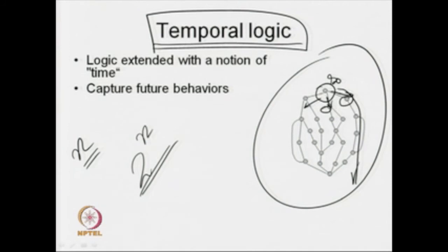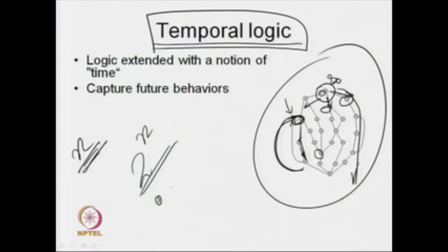And here you just see that I am in this state at a particular time. Now, here the time is different. Again you see that here I am going back to this particular state. So, this is the execution trace, going back to this. Now, this particular state basically gives the binary encoding of my n input symbols, because I define this state with these particular signals only. Either this signal is high or the signal is low.